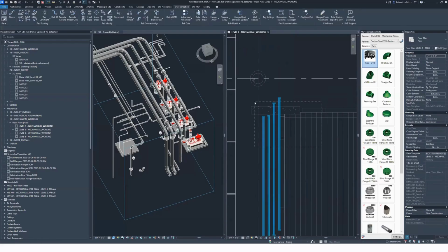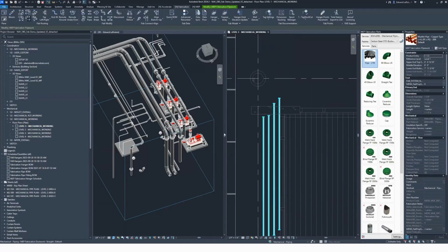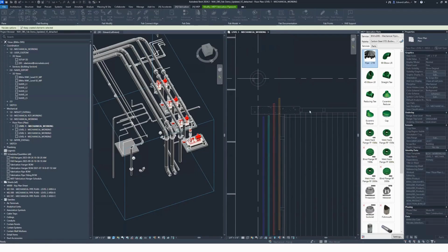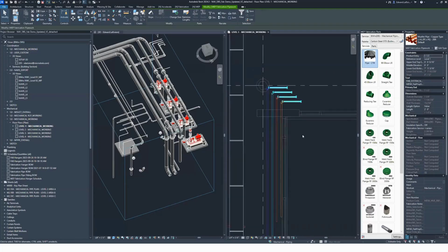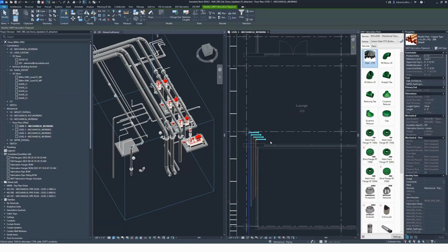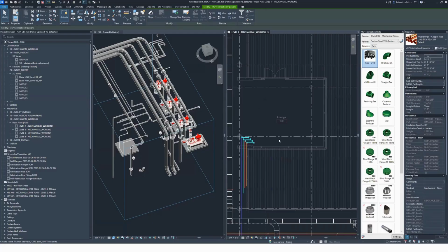So if I grab a whole rack of elements and I start leveraging those same exact fabrication elbow tools, I can actually start turning that entire rack all at once. It looks like it's going to break. Trust me, it won't. It's actually going to give us a perfectly splayed out section here, maintaining any of that spacing we already have. You'll also catch it's maintaining that selection again. We're going to get right back into that really neat workflow of leveraging Revit tools alongside Naviate tools.